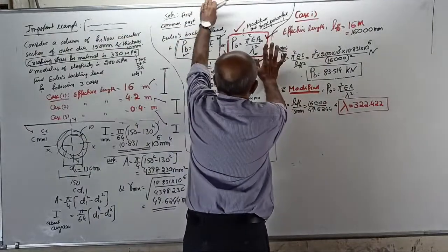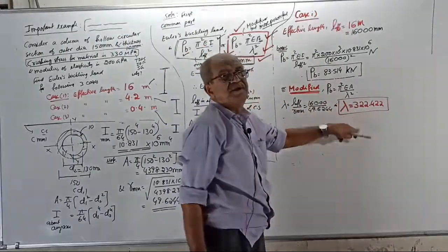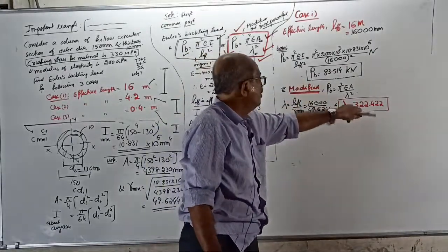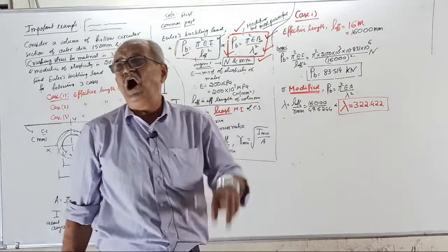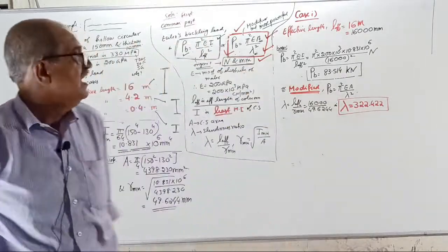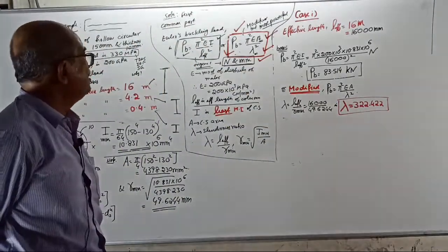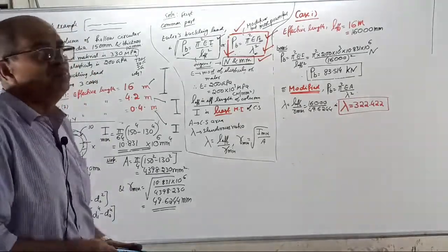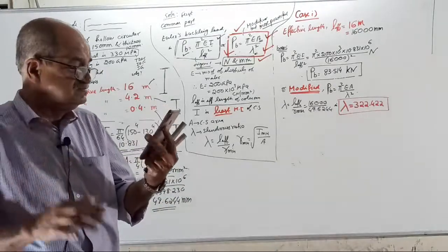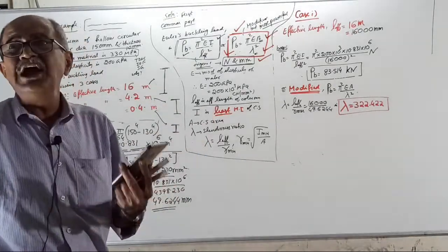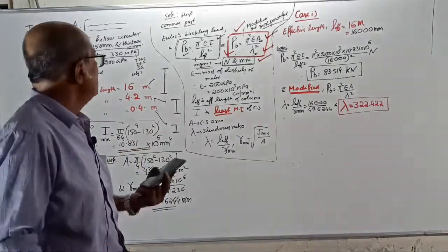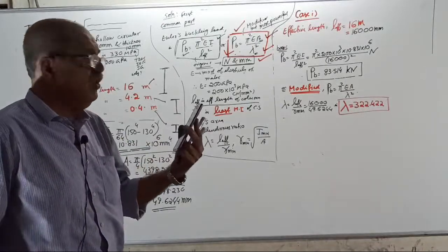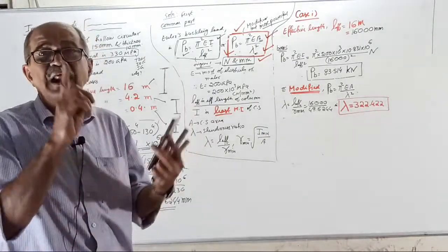This is strength of materials. So that only will tell you this is a dangerous column. According to IS code, is it a short column or a very, very long column? Tell the answer. They told more than 180 is ruled out. So then only you can make out 322. So this column, IS code will not permit you. It is a very, very long column.